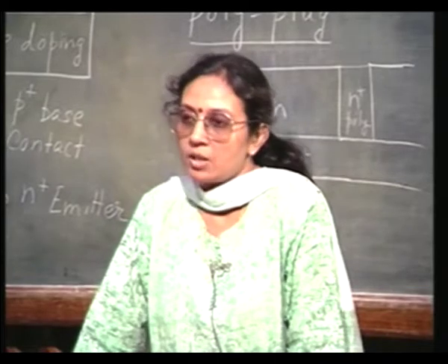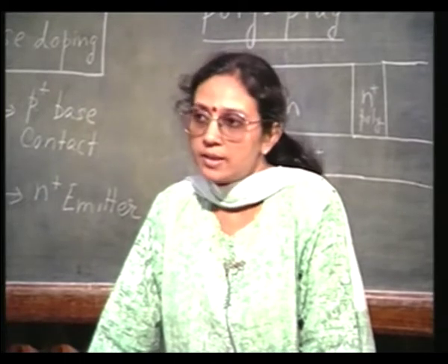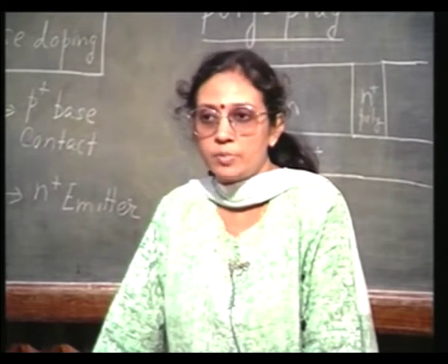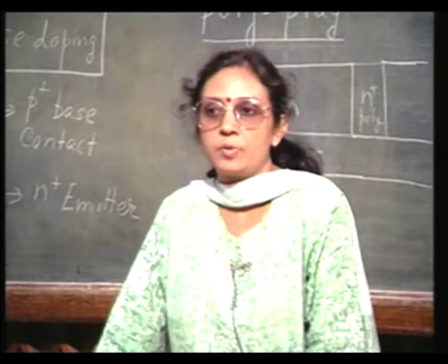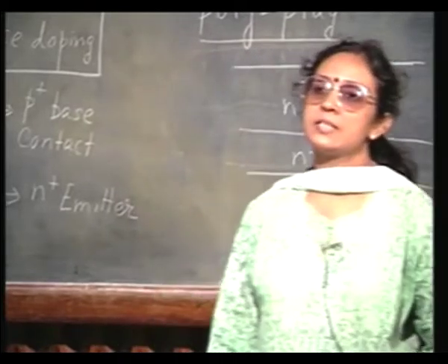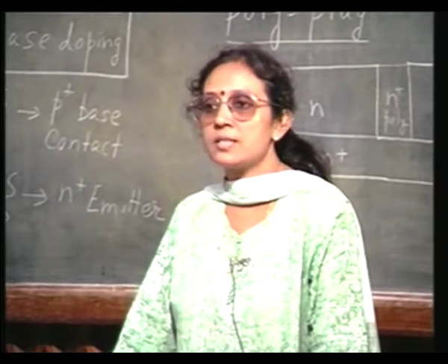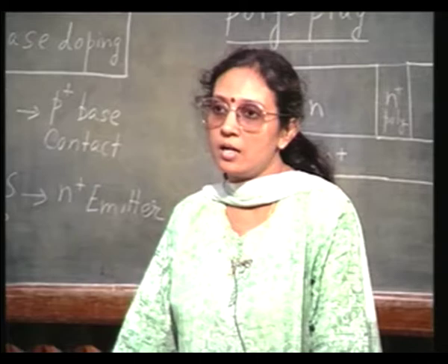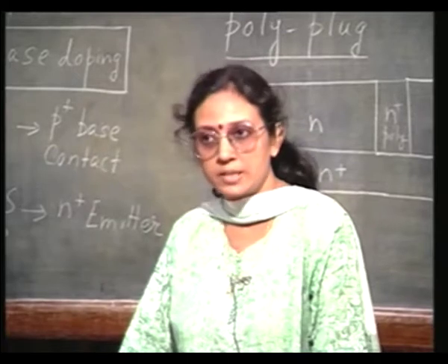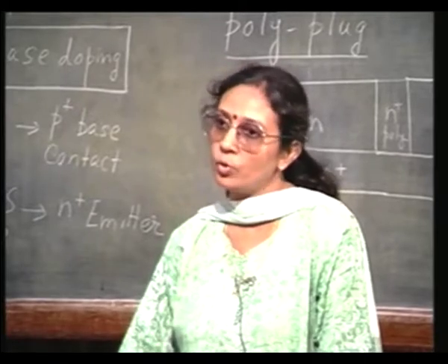That is, the major problem is the base region. There is no compatible step in CMOS process flow. The base of the NPN transistor must be a separate step. Okay. Of course, the collector region can share the N-well. You can reduce the collector resistance by having an N plus buried layer underneath the N-well, which will also help in cutting down the latch up problem in CMOS. In that sense, these two steps can be merged together. The buried layer can serve both purposes.